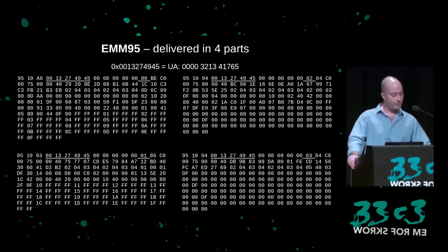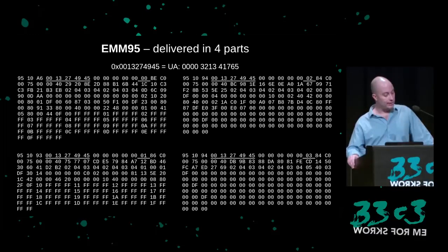When the next part, part 1, is received, the existing authorization data within the ACP from part 0 is hashed along with the data in part 1. If the result is correct, then the authorization from part 1 is copied into the ACP alongside the existing data from part 0. If the result is incorrect, then the ACP's authorization is erased. In this way, the 4 EMM messages are linked together, and if anything is modified within any of the EMM messages, the authorization will fail.